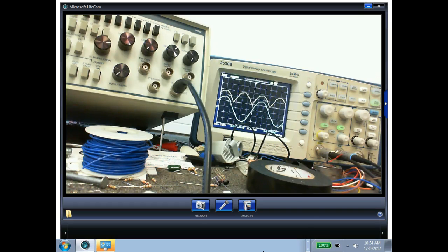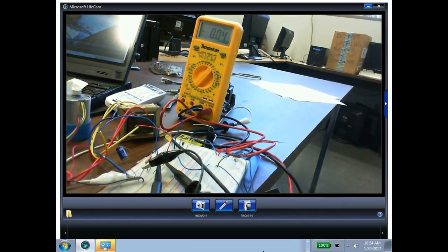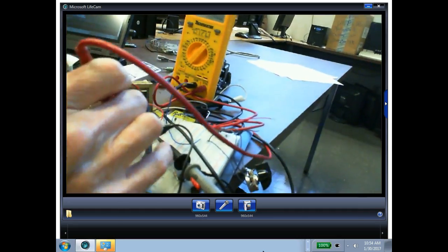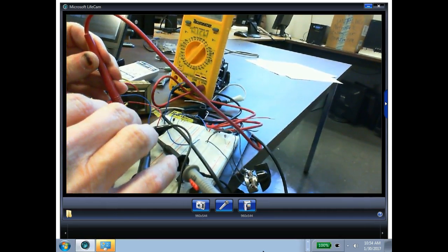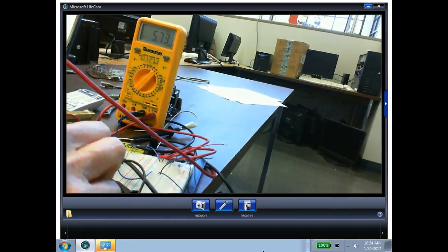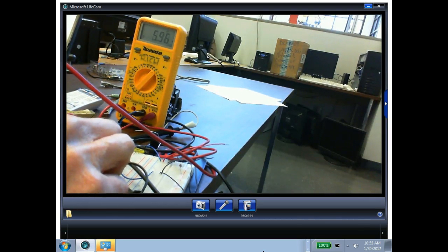So right now we're doing what we call an unfiltered, unregulated power supply. And then we're going to add a filter, and this will turn this into unregulated DC. You'll probably notice my DC voltage shoots up a lot. The 2V peak over pi formula goes out the window. So here's my DC. What do we got? I'm going to come over and put my capacitor across there. Take it off.